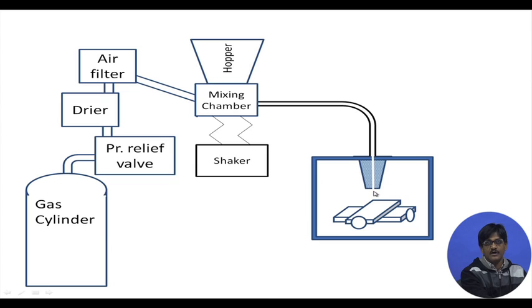So here you have atmospheric pressure. So it will have a particular output velocity. Here what happens is, as the air is coming out through a very small diameter and expanding here, the pressure energy gets converted to kinetic energy, so it develops a very high velocity.